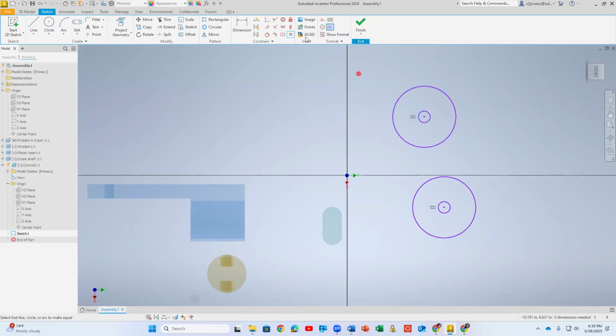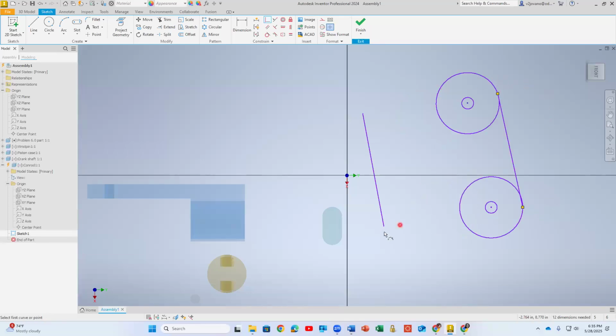These two, oh, the other one was parallelism. That's why this one didn't work. So you see, I put all of these and let me see which dimension they want to have. Okay, that's it. So for the line, I can put lines outside, another line outside. And then I like this feature. It's called coincident. I say this point at the end, I want that point to be on the big circle. And this point, I want to be on the big circle there. Same for this, point to a circle, point to a circle.